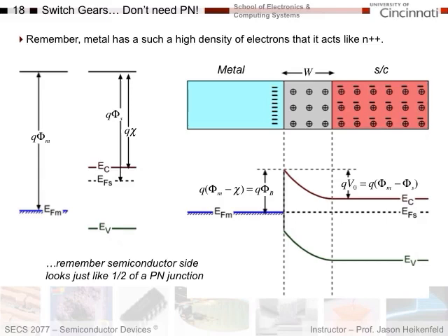And if you recall, when we set this Schottky contact up to get a reverse bias, we would want to put negative voltage on this side, which raises the bands up and further increases the depletion region this way. The key thing we said is that even though I raise the bands up and get a steeper slope, I don't get much current because I'm limited to the reverse saturation current of holes moving here.